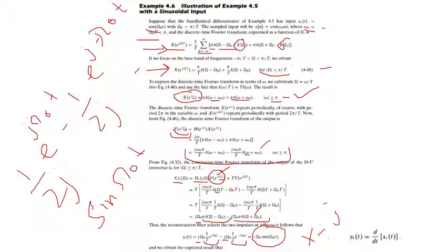Which is the derivative of cos. So what we have done here is take the Fourier transform of the input signal, that was cos. We pass it through the differentiator system using its frequency response, and then finally we reconstruct it and verify that our output is minus ω0 sin ω0t. So this is the overall system that we have implemented. Let's move on to the next slide.